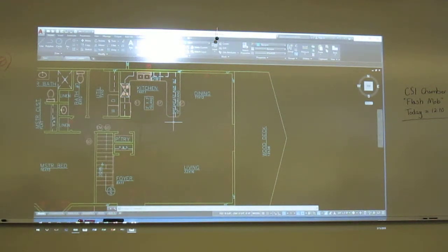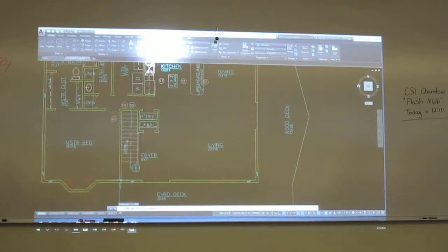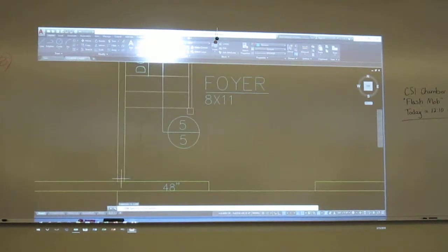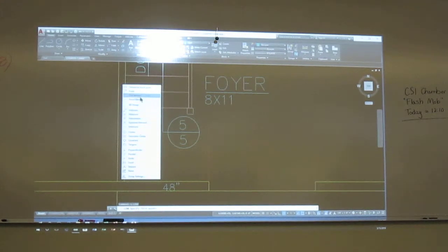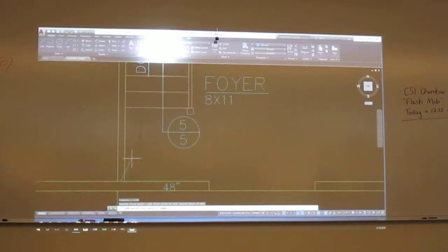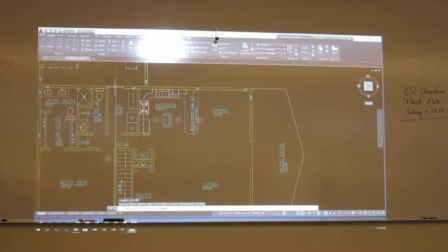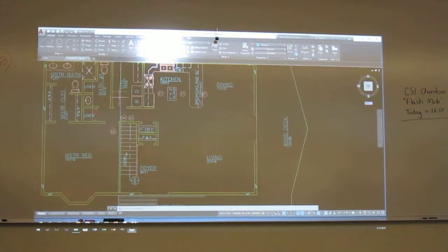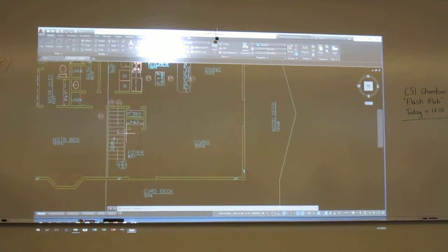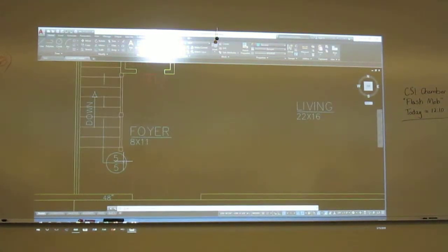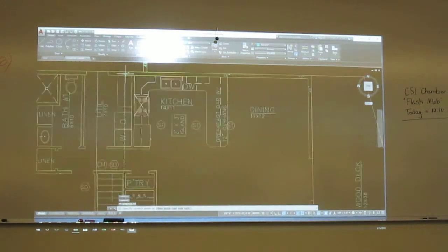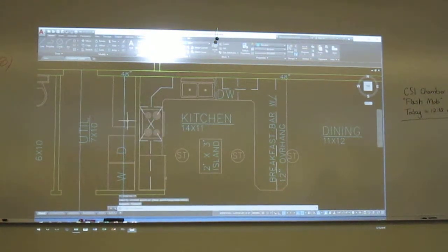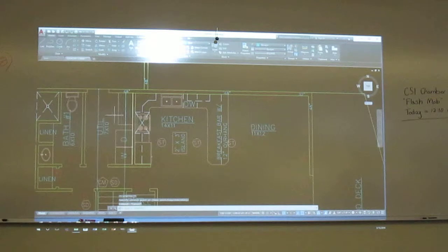So how am I going to get that zone? Well, I do it right here on the floor plan. So I'm just going to come in here and draw a line, and it's probably best to do the center here. So I'm going to do the mid-between two on this wall, and I'm just going to carry it all the way to my other wall. So I just came right on the edge of my marker and shot it through. Okay. Then I'm going to get on the other side of my steps. Okay. And let me just draw this one in, and I'll take that one all the way through to here. Okay, so now I've got my 2 zones delineated.